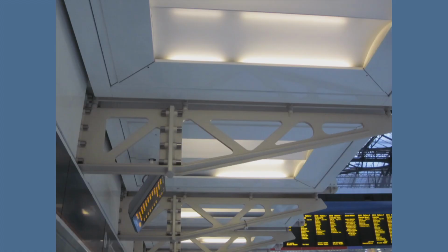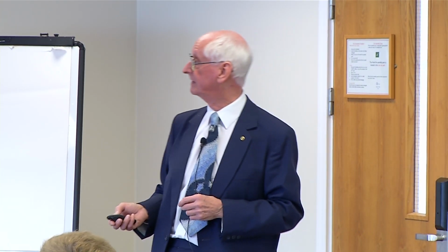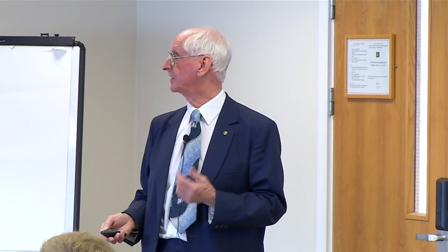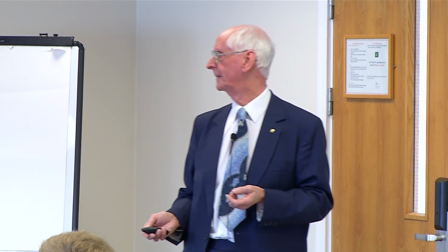This one I like, you probably see it's a railway station. In their cantilever beams, they've got bolts through here, but they've got cylindrical heads and nuts, and hexagon socket fixing in the nut to actually hold it all together. So someone took a great deal of trouble to do that, and pride, and it looks lovely. You can't even see the hexagon head. So people can do things right, but they can also do things wrong.